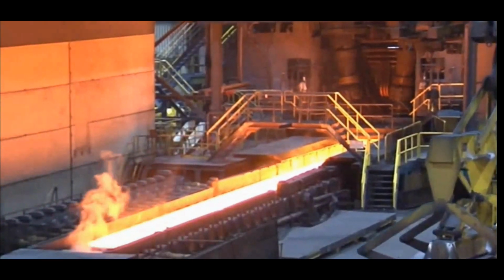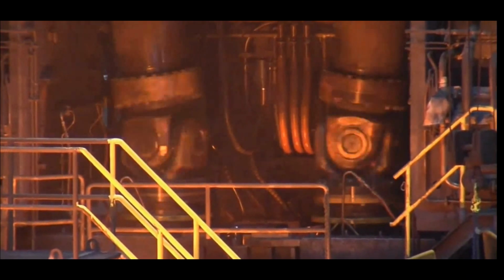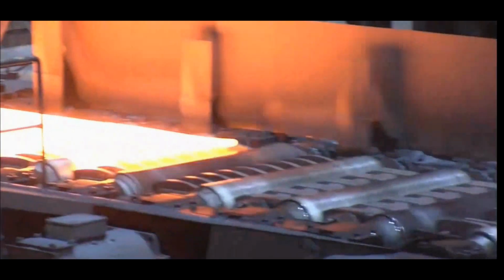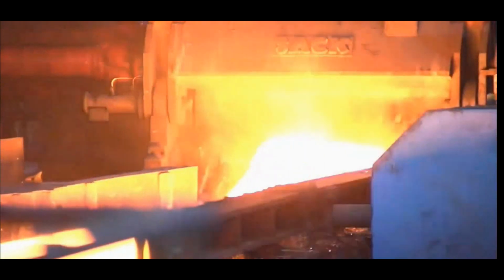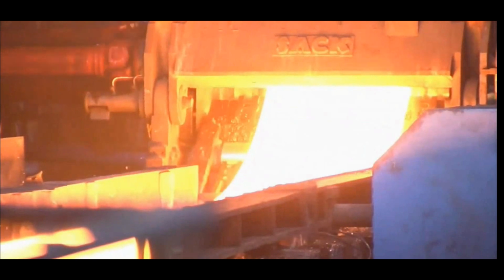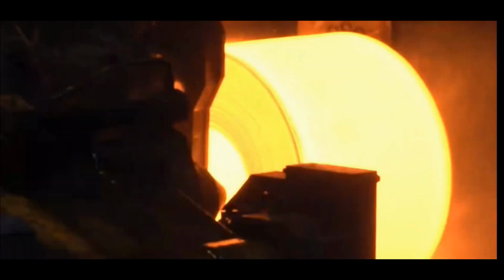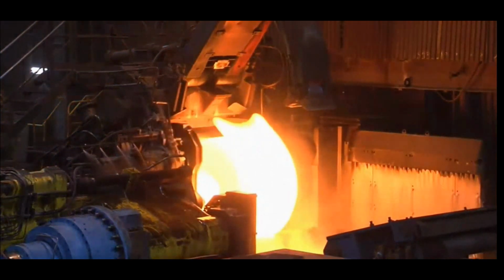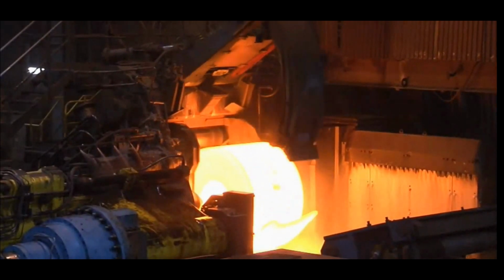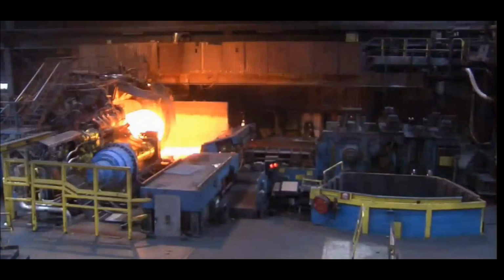In order to control the width of the material, vertical rolls are used. The material is now called transfer bars. After the roughing mill, the transfer bar is rolled up in a coil box. The coil box's primary purpose is to save space, but when inside the coil box, a temperature equalization also occurs. The temperature difference between the ends of the material is minimized as the transfer bar is coiled together. When the transfer bar is removed from the coil box, it has a temperature of about 1050 degrees centigrade.